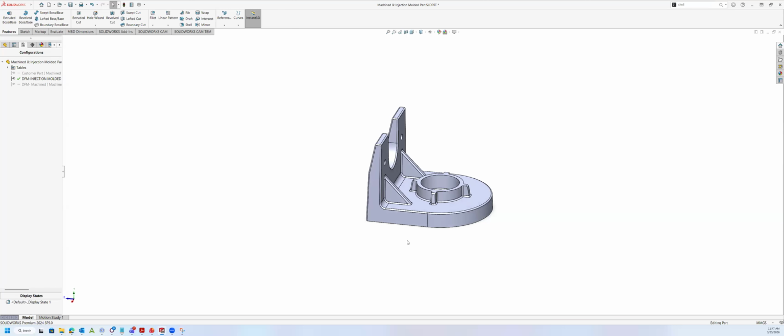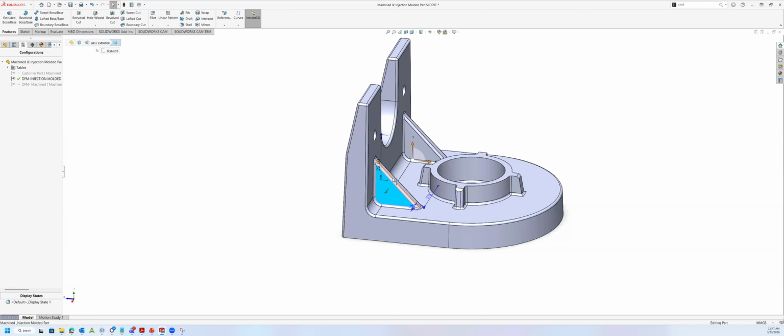I mean, you can do both if you really want to. You can increase the internal fillet and as well incorporate these ribs to increase the safety factor. However, depending on the application and how much force is applied, the fillet alone might not be enough though. Sure. So it just depends on how much force is applied or how much this part is exposed to.